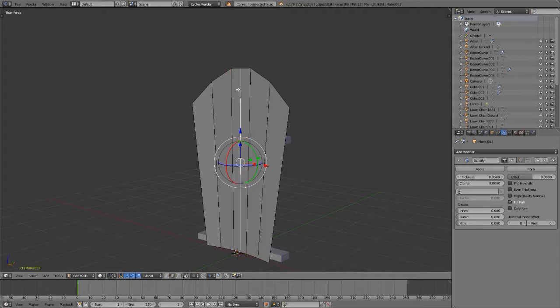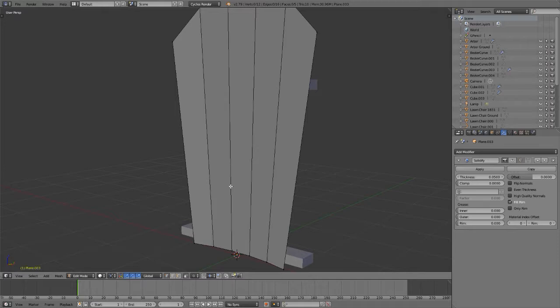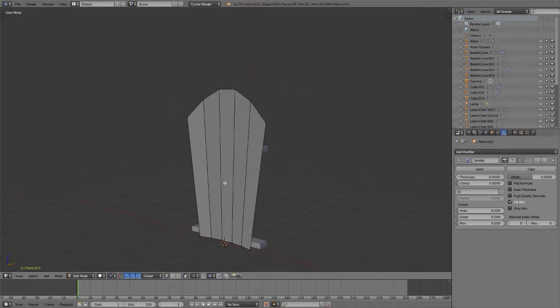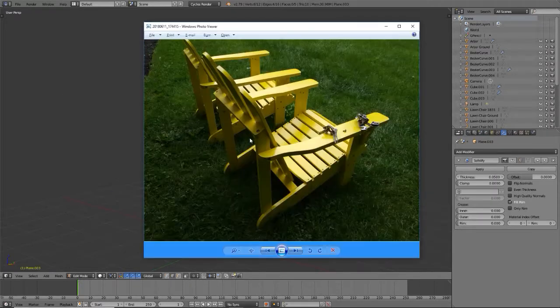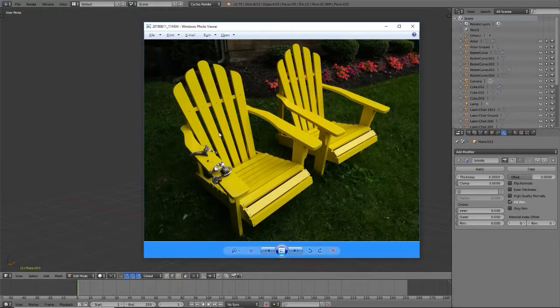E. Select the edge I want to dissolve. Dissolve edges. It dissolved. And its vertex is gone. On the top and on the bottom. I wanted this. I want now for this to separate correctly. Control Tab E. I want to select these guys which represent the splits. What size is that split? Do you and I agree it's about a third of the slat in the middle?